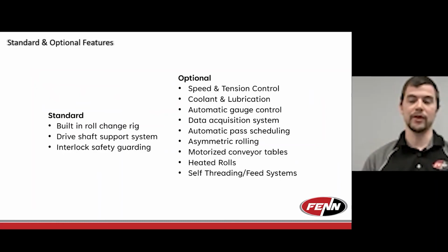If you're running continuous coiling with tension, things like that are better at eliminating bowing, and having your rolls spin at different speeds can cause other characteristics in the system to occur that may not be good, which is why, like I said, this is more of a unique application dependent one.